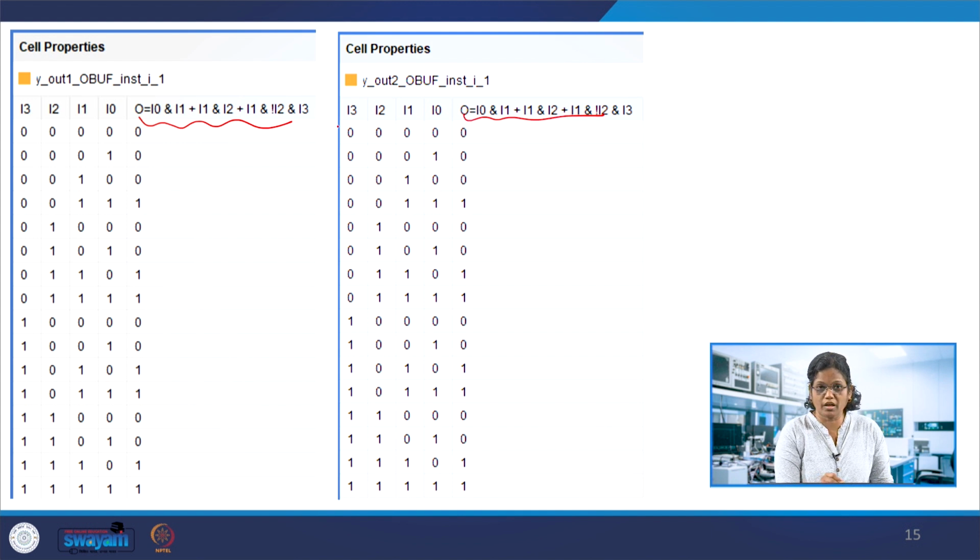The lookup table inputs are basically from the inputs to the gates. So the gates, the primitives instantiated, are converted in the technology schematic into lookup table information with the Boolean expressions here, and this Boolean expression is even minimized using a Karnaugh map, and then this is implemented. So the output you will get here.